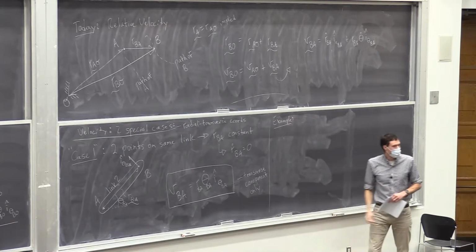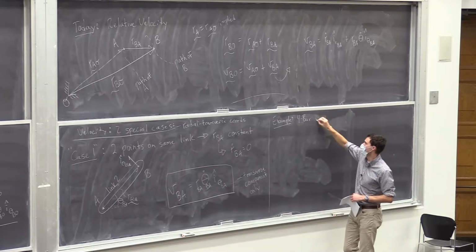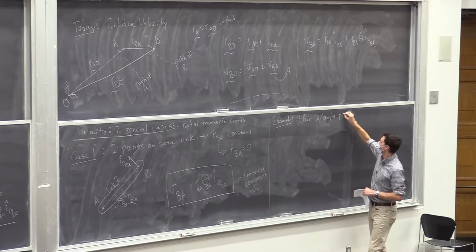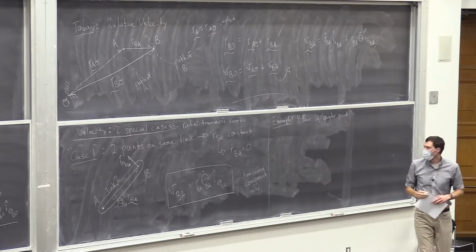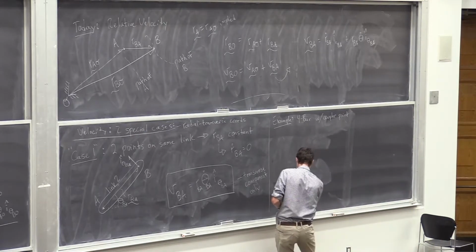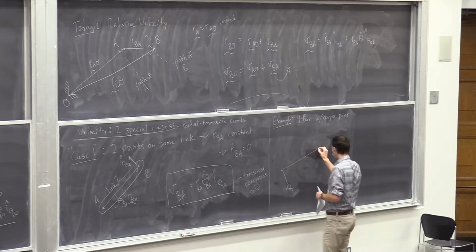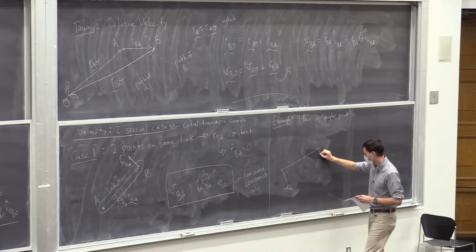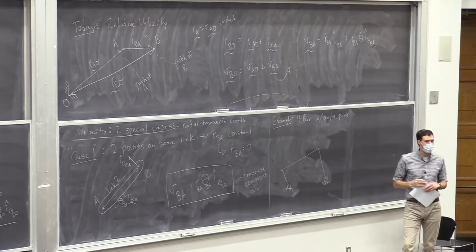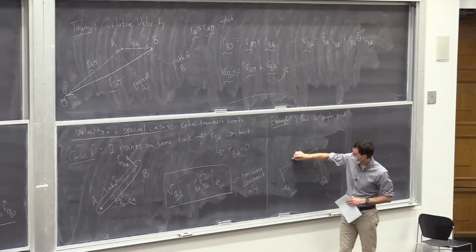This is going to be our first mechanism full velocity analysis. We're going to do a 4-bar, and it's going to have a little extension on link 3. So let's sketch out a 4-bar. Okay, try and draw it similar to mine because the shape that you draw it affects these velocity vectors and everything.